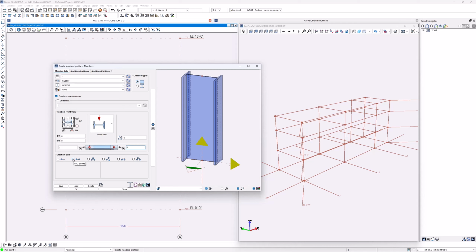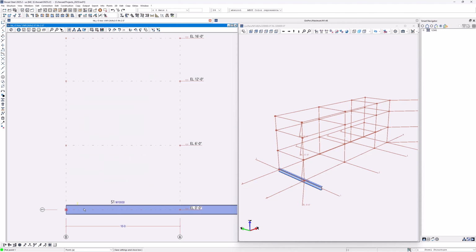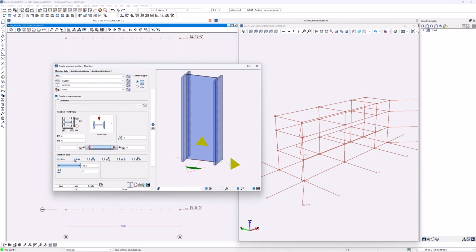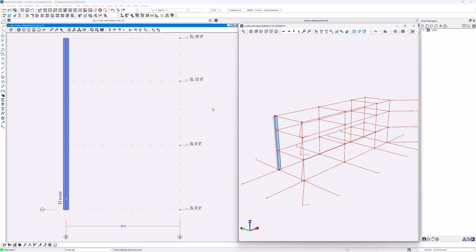An element could be created over one point. Good for a column, but of course, since there is no endpoint, we would have to enter the length of this component. So if I say this is a 16 feet component, and I press pick one point over there, or one point over here, I'll see that component coming in. If now I say, no, I'm going to create that over 2 points, start point, end point, there it is. Or start point, end point, there it is.